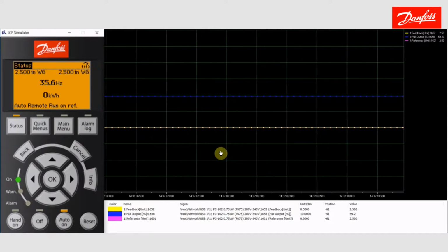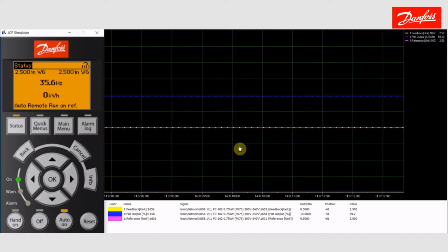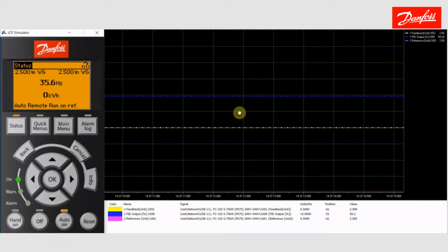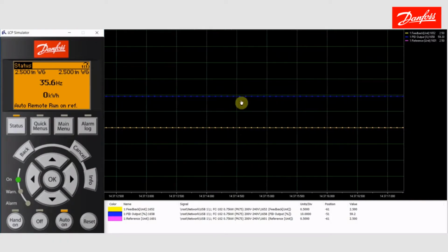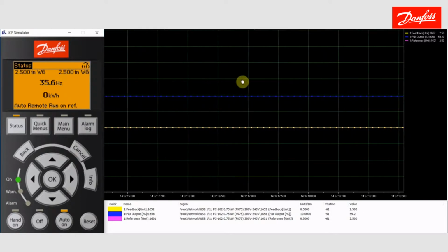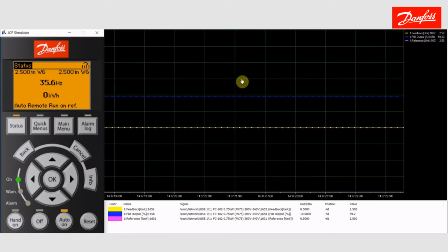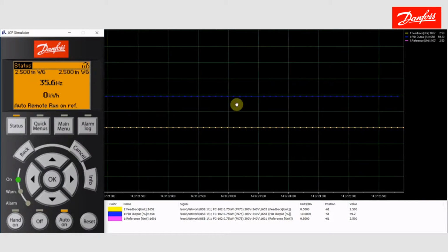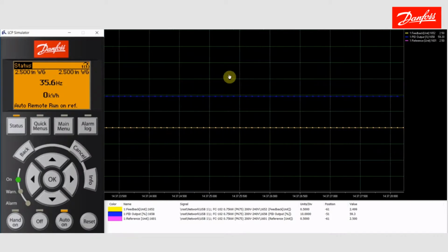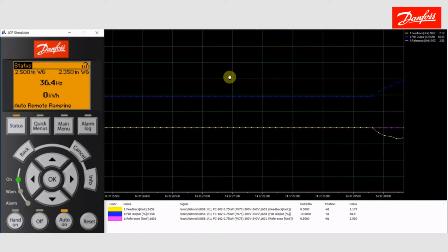You'll find a lot of times that it comes up with acceptable values, and you don't have to do anything further. And you can always do the auto tuning and then tweak from there. A little bit more gain, a little more or less gain or integral time, and see how the system reacts. This particular system right here, I would make no changes. It seems to be operating very nicely.